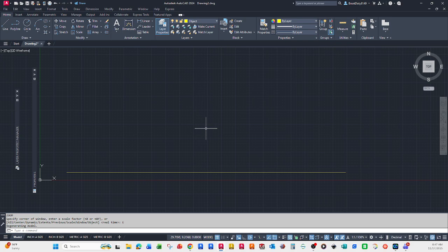So basically when you start a drawing, think about what units you're using. Do I need to change my limits? Then if you need to change your limits, you change your limits. Then when you're done setting your limits, and of course, you remember, you go into limits, and 0, 0 is fine. You hit enter. Then you decide what the next size needs to be.